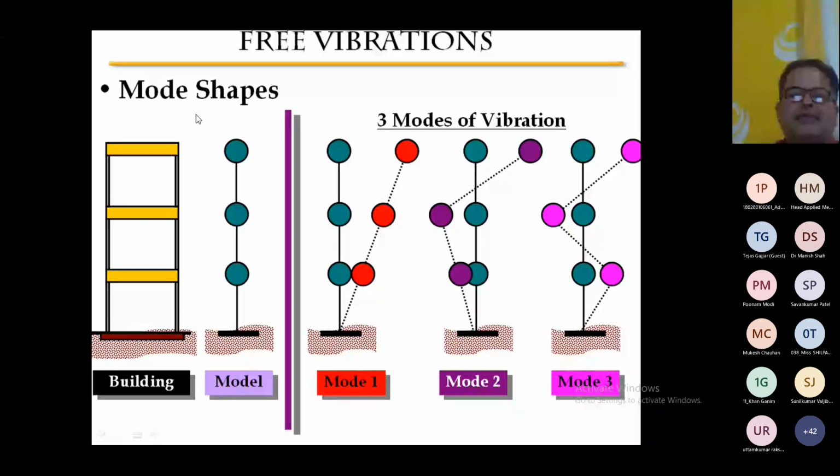So here what I'm saying is, the mode shape is a deformed shape, and here it is a 3 degree of freedom system. So I'm going for the spring mass model or the stick model. Now I'm saying this is the mass m1, m2, right? These are the lumped masses at the floor level. This is our assumption, remember, right? We don't want to make our calculation complicated, right?